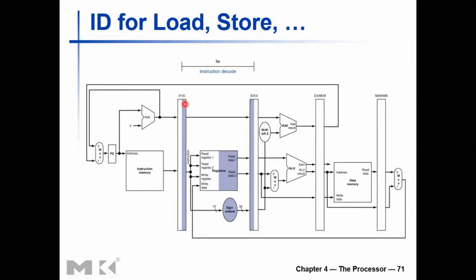So now in the bigger picture, you need to keep in mind that we are pipelining this CPU to get better throughput, but in order to pipeline, we are adding these extra time overheads. These overheads would not have been there in a non-pipelined multi-cycle CPU or a single cycle CPU. But we are adding these overheads in order to get the pipelining done properly. The pipelining itself will give us a massive throughput benefit. But the latency for the instruction to spend inside the CPU, we are increasing by adding all these overheads.